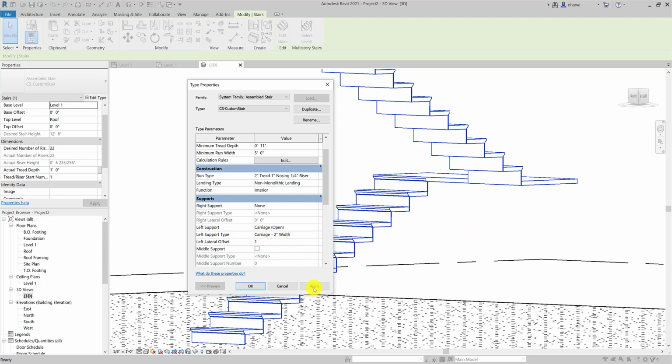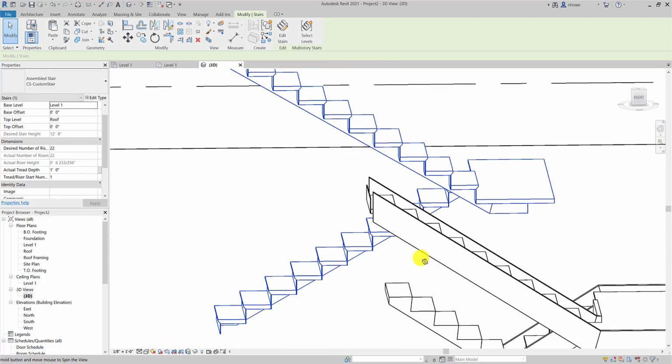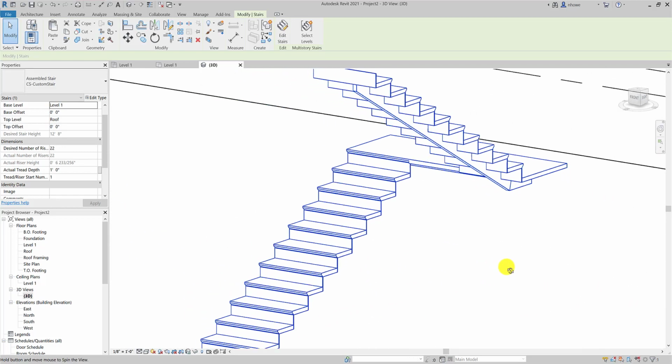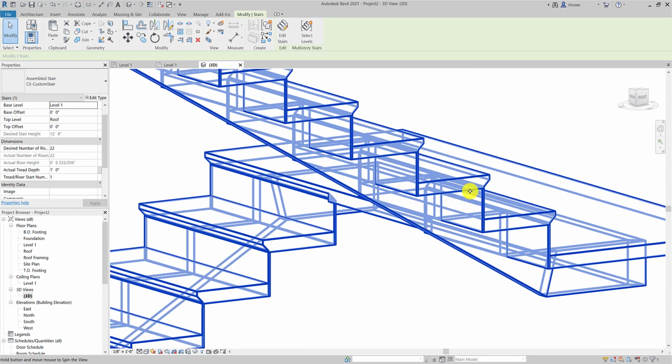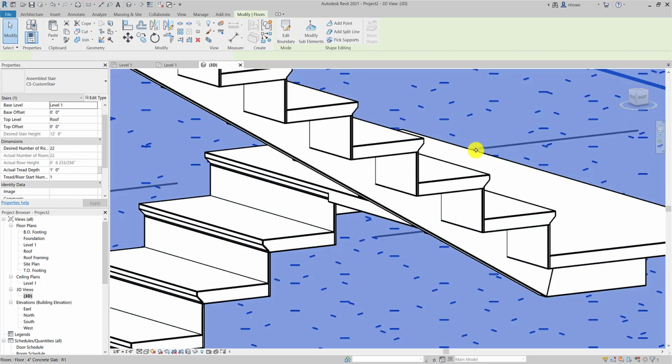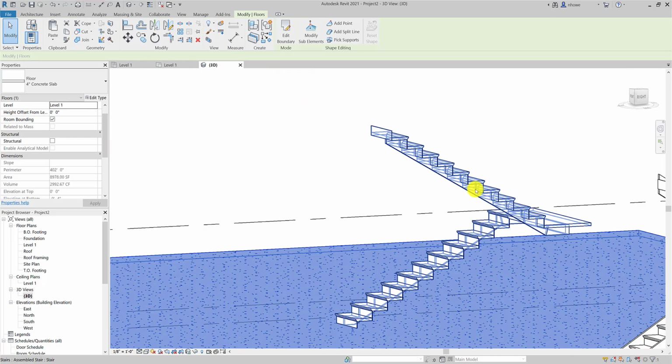You can do all kinds of crazy things as far as modeling in Revit. It doesn't mean that it's structurally stable. So if I wanted that to kind of look like it's floating, now this would have to be some plate steel, right? To actually make that work.